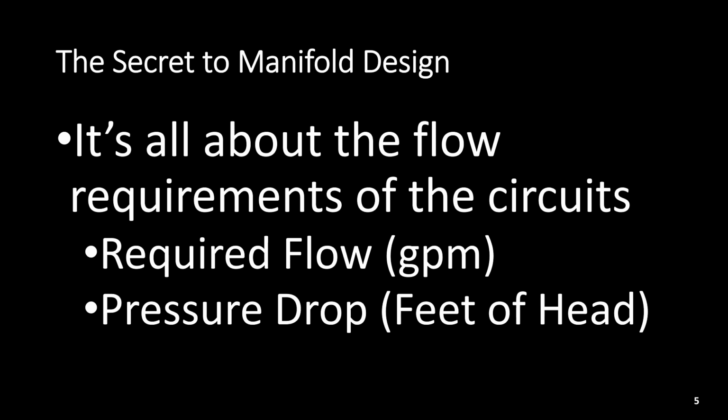However, the secret to manifold design is all about the flow requirements of the circuits. That's both the required flow in gallons per minute, and equally as important is pressure drop, because pumping energy, I've seen so many jobs where pumping energy is enormous. I go back some 25 years and I did an energy audit in Pennsylvania on a geothermal system. It cost more to operate the circulating pump than it did all the heat pumps combined. And that just points to a lack of attention to pressure drop throughout the system, but also importantly is the loop field. So we're going to stress that as we go forward today.